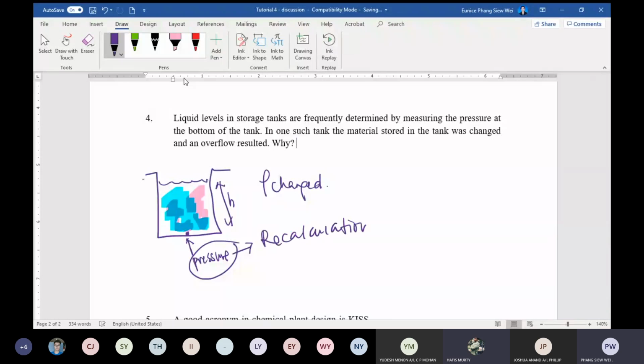And then I suggest you put up the calibration table, so that when people use material A, they need to use this, and when they use material B, they need to use this. Because when you calibrate, you calibrate the pressures to tell you the right thing, since it will measure at a different pressure.